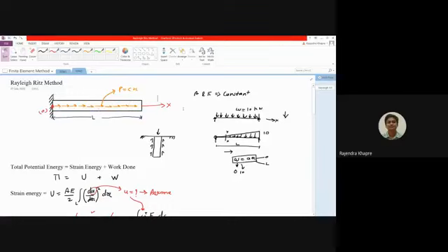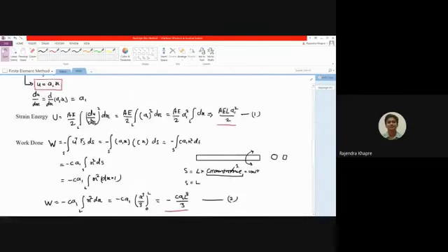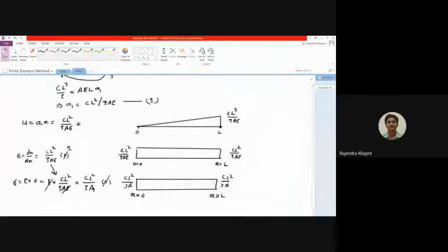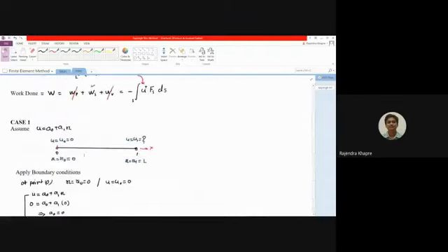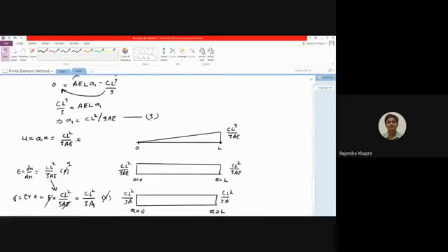Now, since the force is increasing, you cannot have a variation of stress as a constant. So your stress will never be a constant. And what you are getting over here is that your stress is constant irrespective of your location. So the meaning of this is, whatever you have done till now, it is not correct. Why is it not correct? Because you have assumed a polynomial like this, and this polynomial is not good enough to give the appropriate results. Although it is giving you results, these results are not matching with the actual type of problem. Now, how to deal with this problem?